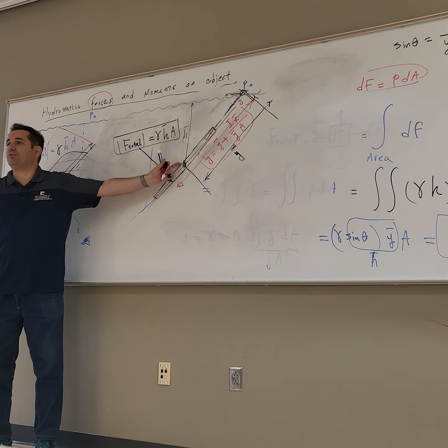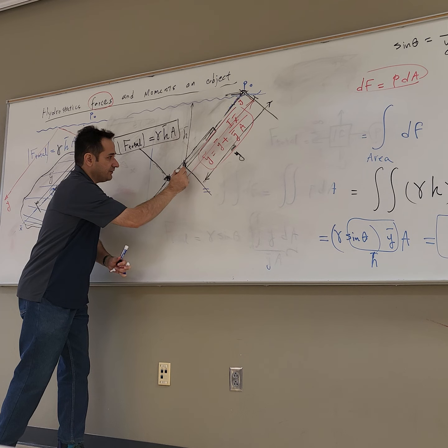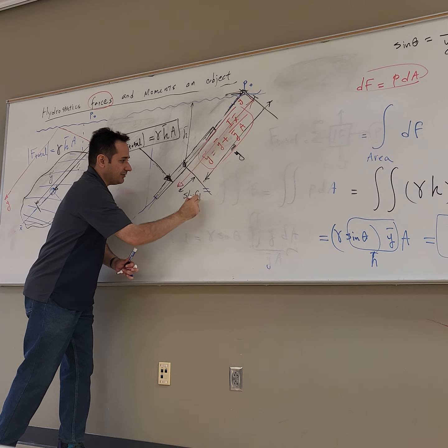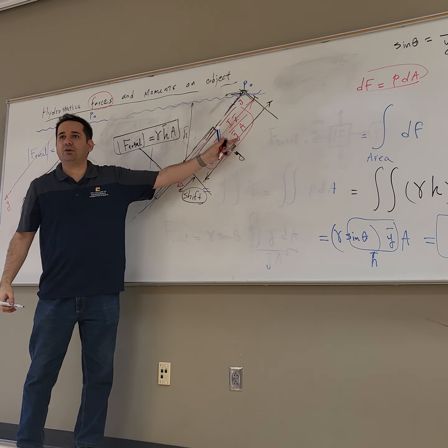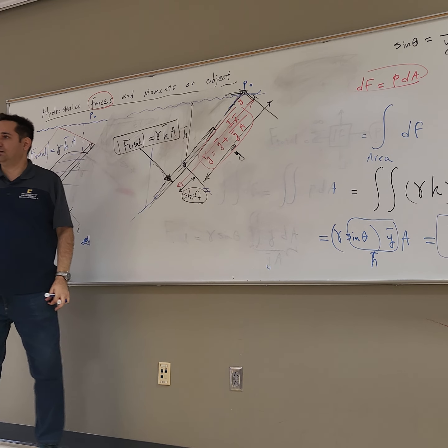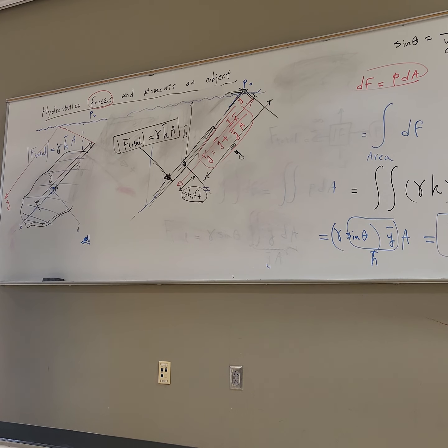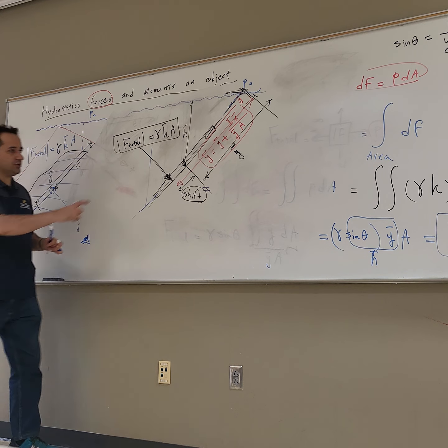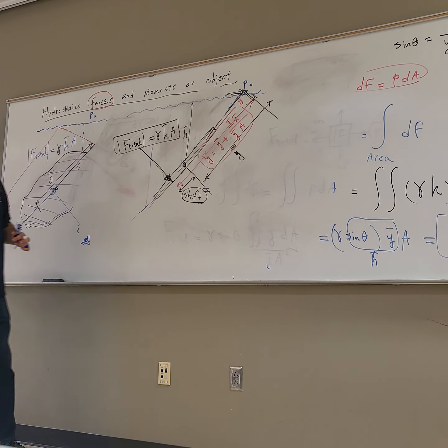The location is not y bar, it's y bar plus a little bit of shift. You see these pieces? Your shift. It goes a little bit down. You see that? How much does it go down? I x bar divided by y bar a. So that's a mathematical proof for the experiment. If you go to the lab and put that razor at some point, it's below the centroid. How much below? I x bar divided by y bar a.